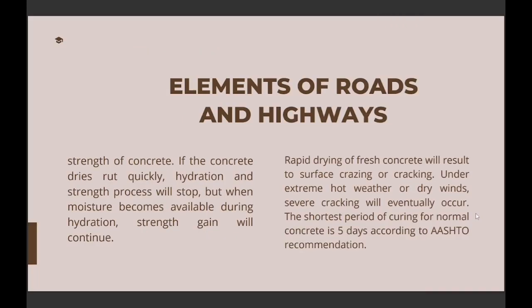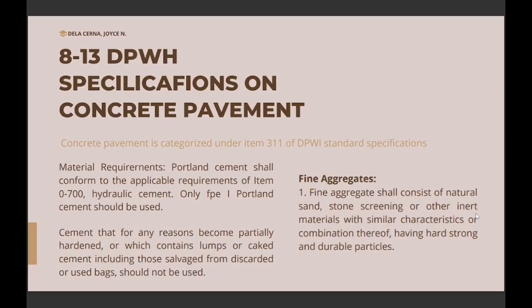Elements of roads and highways. Strength of concrete. If the concrete dries out quickly, the hydration and strength process will stop, but when moisture remains available during hydration, strength gain will continue. Rapid drying of fresh concrete will result in surface crazing or cracking under extreme hot weather or dry winds. Severe cracking will eventually occur. The shortest period of curing for normal concrete is 5 days according to AASHTO recommendation.